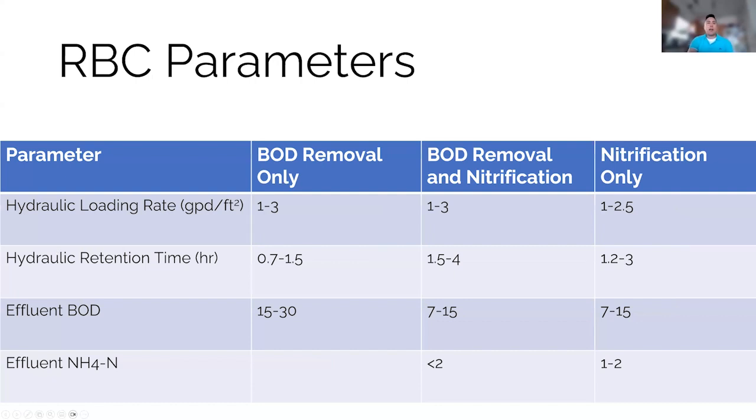These are a couple of quick RBC parameters. A lot of the time, just like trickling filters, you want to be able to calculate the hydraulic loading rate and the BOD loading, and also for RBCs themselves, you're more likely to treat for nitrification and have a hydraulic retention time.